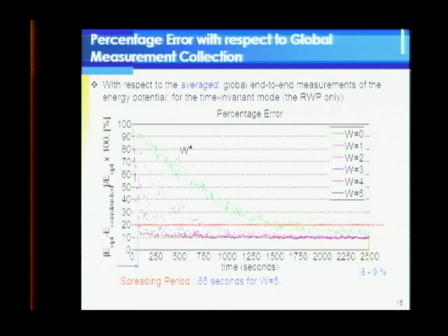This is coming from the fact that we're using a uniform grid size. As I showed you in the beginning, there was about 15% error towards the base station, and overall 5% error, that comes from uniform cell sizing. That's one reason why you have this error.